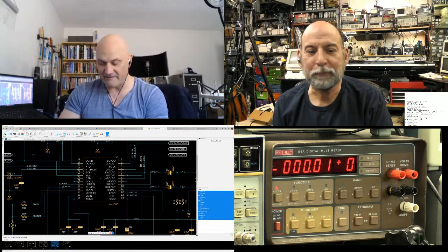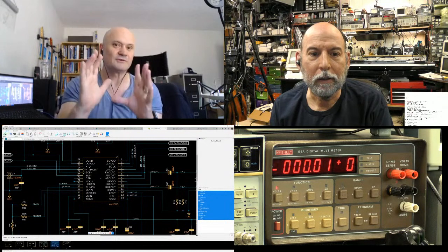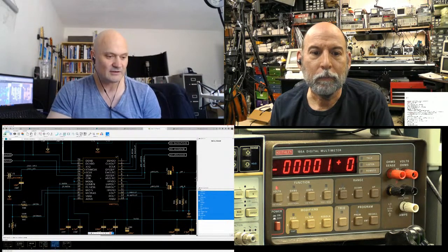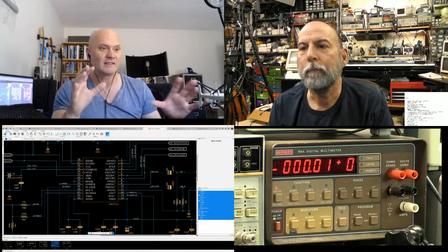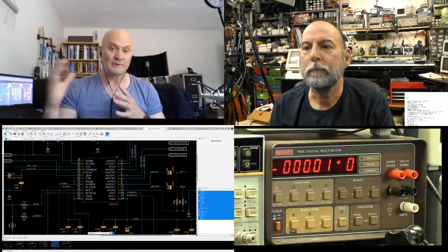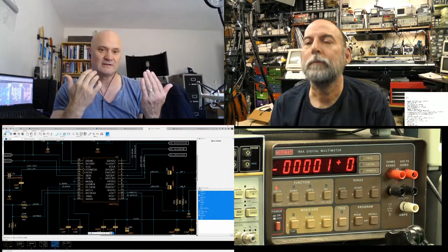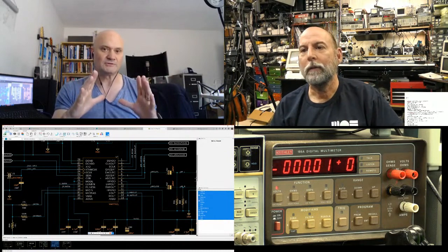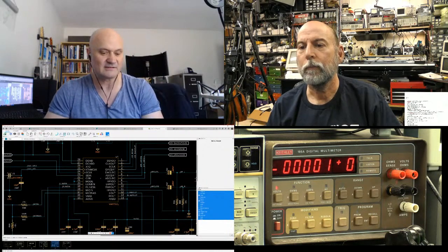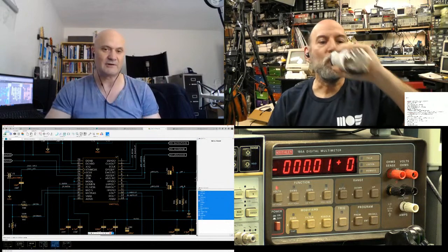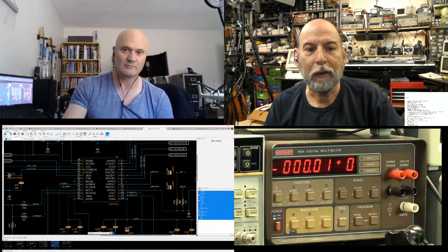Yeah. Well, I found some other reference designs on the web. I found a synthesizer module manufacturer called Mutable Instruments, and all their designs are open source, which is awesome. They design their boards in Eagle. So I was able to open up one of their synth modules that actually uses this chip with an STM32 microcontroller. And they just tied the pins together. If you have the same sample rate for read and write, just join them together. It's so obvious in retrospect, but the data sheet wasn't explicit about it.